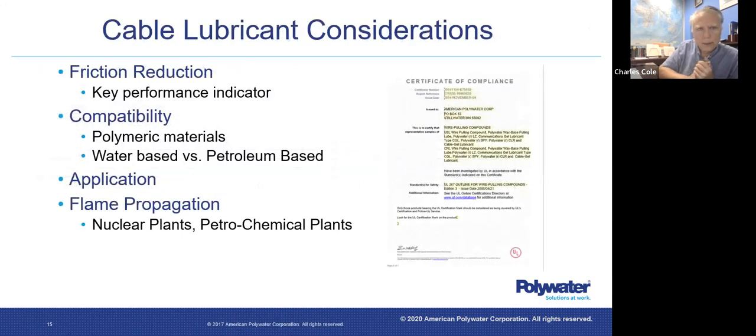Just very, very quickly, cable lubricant considerations. Friction reduction is the key performance indicator, but there are also some other issues like compatibility. The doctor mentioned the use of grease or petroleum jelly.